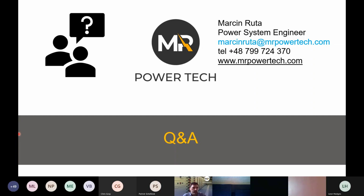So we have 61482, which covers both open arc, ATPV, and box tests. They are both IEC testing methods. So we are selecting our PPE based on IEC tests. And IEEE is just the way to calculate the arc flash, which I kind of make in a Europeanized way, using IEC and the smaller gap distances that we use in Europe.